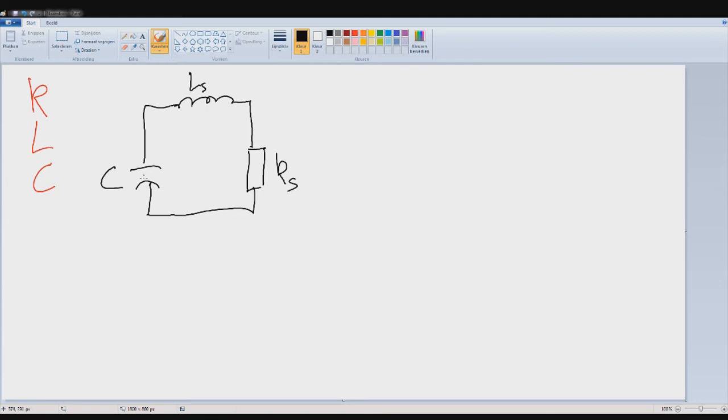Now, you might think, where does the stray inductance come from? Well, as I said, we are using very big capacitance, 24 millifarads, which is a capacitance that the capacitance in the rails, in the projectile and stuff, would almost be negligible, because this value is so high. It would add nothing to it, but as we have no inductors put into the circuit ourselves, or any resistance, it's still there, and it's a little bit. It's a very little bit, but you can see how significant that is.